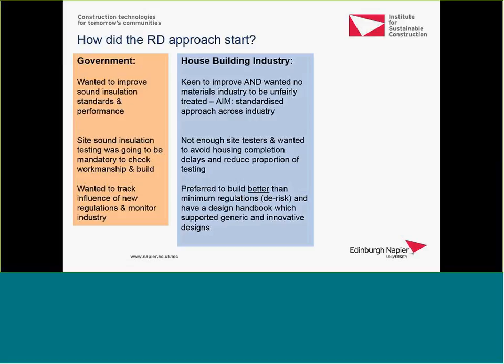But they were also concerned there were not enough site testers for sound insulation testing. They wanted to avoid large percentages of their housing stock requiring compulsory sound testing and reduce that proportion of testing to something more manageable, more like a sample rate. But they also preferred to build better and de-risk. So could they design and build better than the minimum regulations?